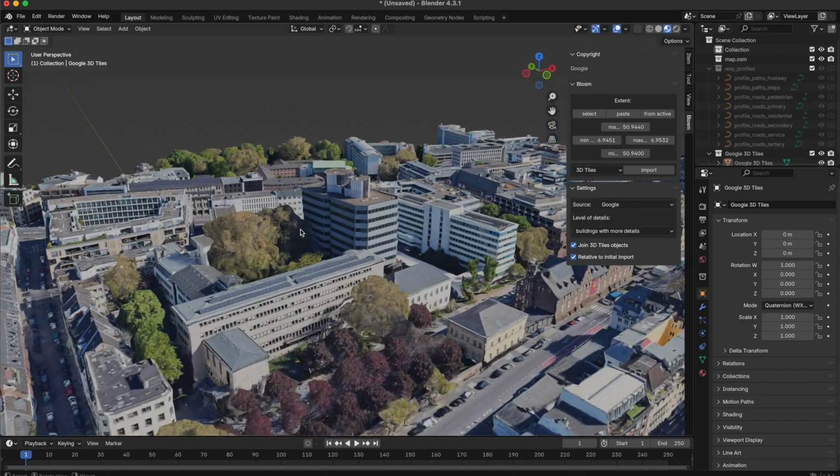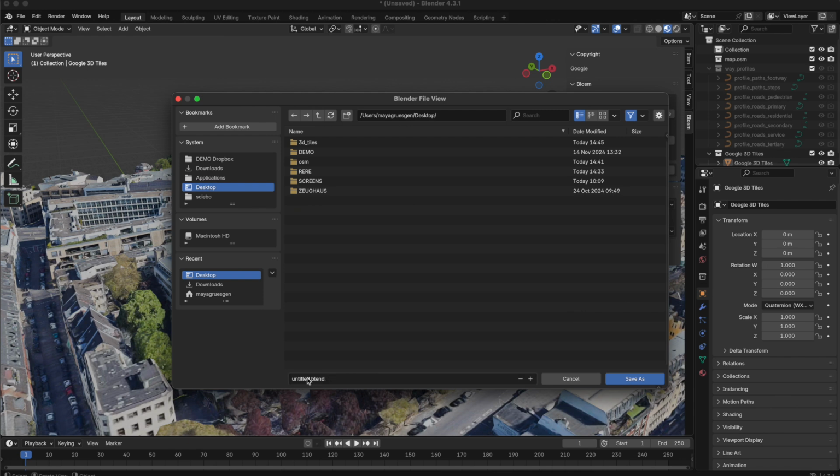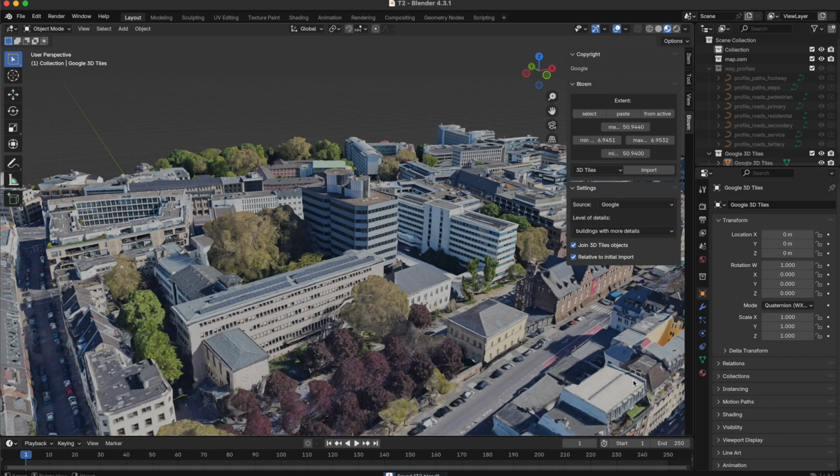Okay, this is in Blender, so we're still not in Rhino. We first save the file as a blend file. Then we need to somehow export this file with materials. I tried a lot of different ways to do this, and the best one I found was to export it as an FBX file. We can import an FBX file into Rhino or other tools later, but to export it we have to fix the materials first.